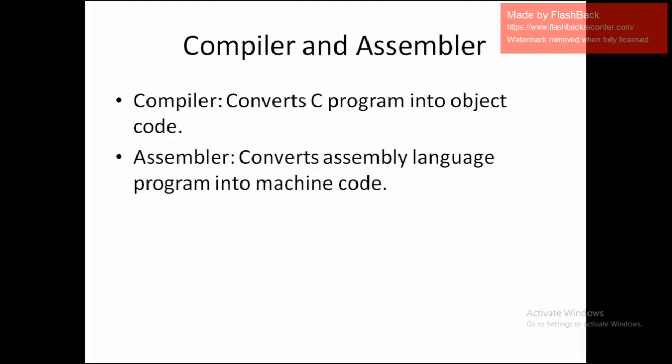You can have a development kit. So into the development kit you can download the hexa code, that is the code generated by compiling this code written in C language or assembly language, that can be converted into hexadecimal values. So that file will be saved with name.hex, so that you can download into the kit, whichever development board you are using.